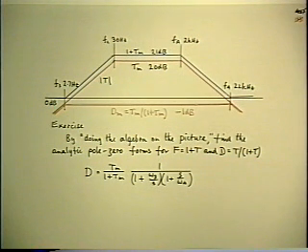Okay, this is the major part of the solution now. We've got the model, the AC model for the closed loop feedback system, injected a test signal, solved for the loop gain, and then determined the dependent quantities f and d. So we've got one more principal quantity to determine, which is the g infinity, and then we'll put the g infinity together with the d, and that gives the final closed loop response. So to find g infinity, we go back to the model.